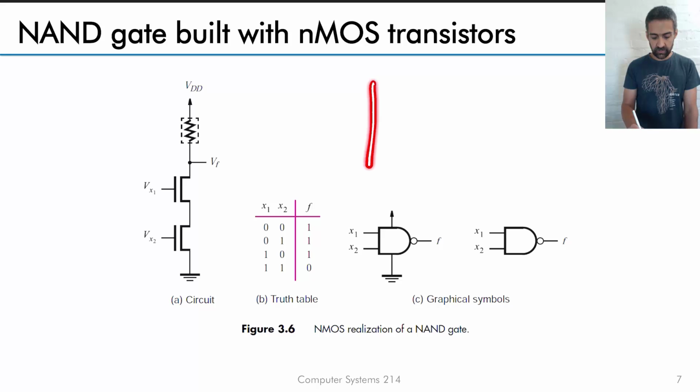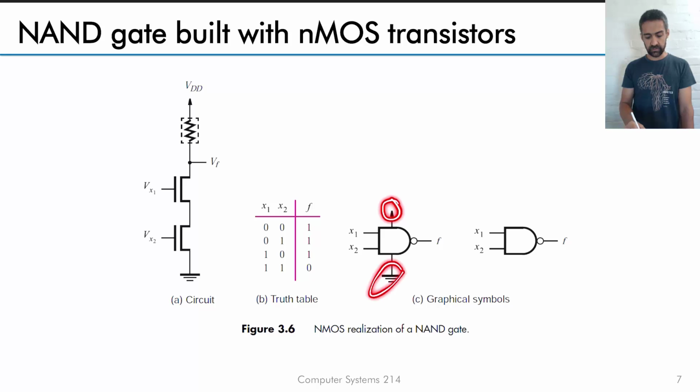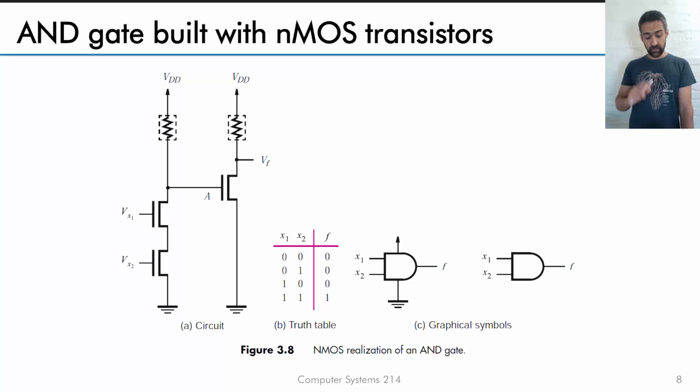If you just think about it for a second, in the practical, you will have a chip. And this chip you'll have to provide 5 volts to, and you'll have to provide ground to. And that's this 5 volts, and that's the ground. And then in between are a few logic chips. And these logic chips will be made up with transistors. Now, this is how you make a NAND gate.